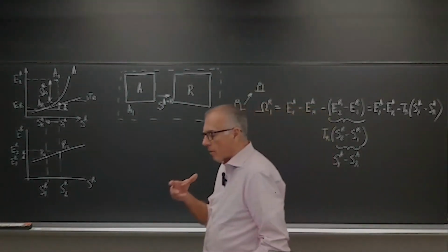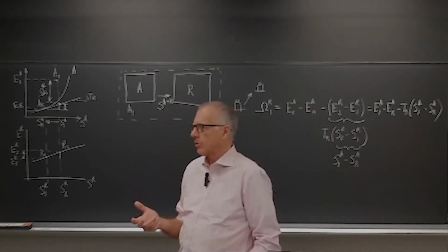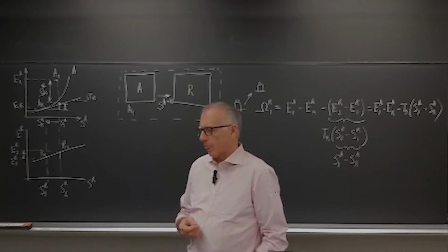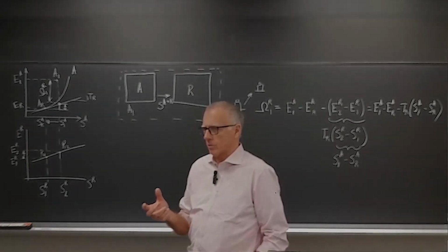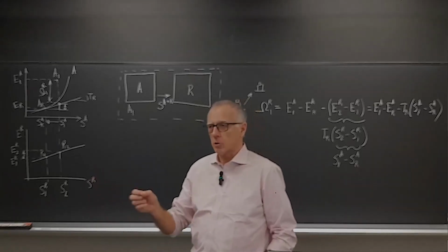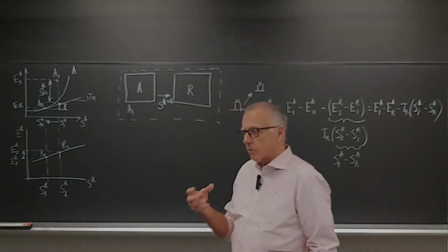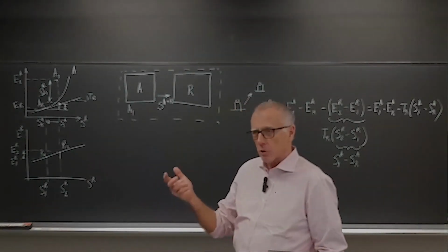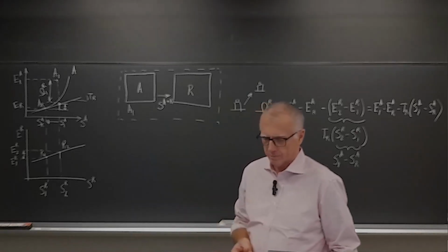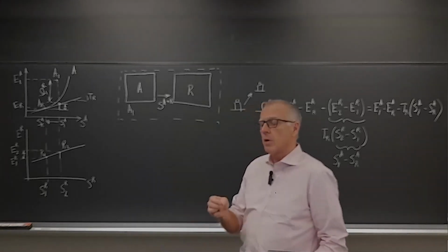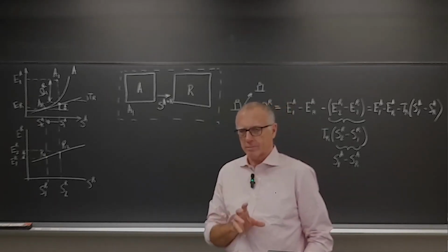So that energy that you are giving to the environment in a typical energy systems application is not a waste. Sometimes you say, "Oh, I'm wasting energy." No, it's not waste. You're using the environment for a very important function. You're using the energy there. That's not where the inefficiency of your power plant is. The inefficiencies come from the internal irreversibilities that are in your machinery.